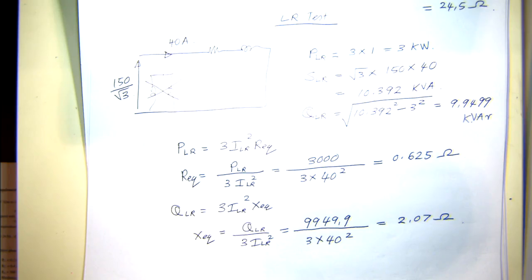So that's the characterization tests of induction machines. Any questions up to that point in relation to the testing methods? It should be fairly easy at this stage since you've done transformer characterization tests, isn't it? So it's pretty much the same concepts. You just have to think of the lock rotor test as a short circuit test and the no load test or the zero slip test as the open circuit test.